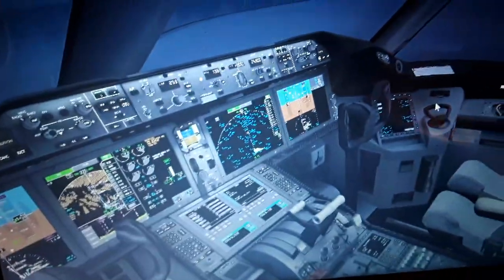Also the FADEC controls the pressurized air from the 5th and 9th stage of the engines. Also hydraulic fluid and air pressurizer for cabin pressurization. Also the left and right wing fuel tank, fuel recirculation is automatic. We recirculate the fuel in flight so it will heat up and won't freeze. Also the oil and the lubricant of the engines is recirculated in flight.